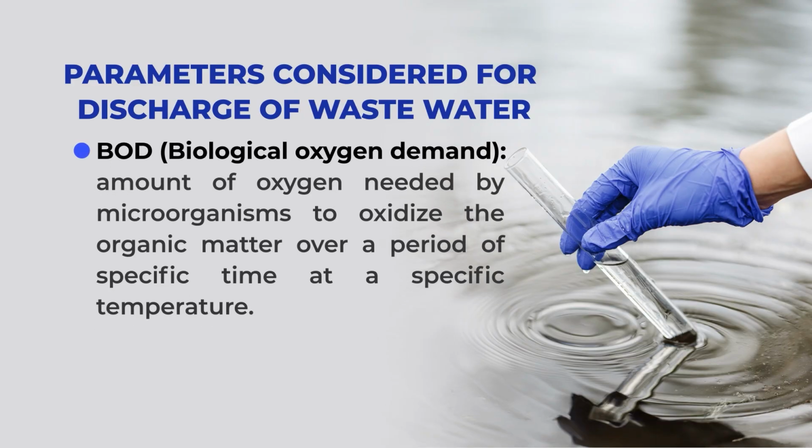So, based on these characteristics, certain parameters have been decided which are to be considered for discharge of wastewater. And these important parameters are like the BOD, that is the biological oxygen demand. So, that is the measurement of the amount of the oxygen which is required by the microorganisms to oxidize or decompose the organic matter over a period of specific time at a specific temperature. If it is done for 3 days, then it is called BOD 3, if it is done for 5 days, it is called BOD 5.